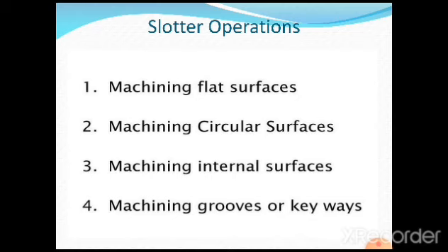Machining internal surfaces can also be done. Suppose I want to go for internal keyways, even those can be produced. Machining grooves or keyways, as I have told, whatever the type of groove and keyway, depends upon the adjustment of the stroke length and the profile of the cutting tool being used.